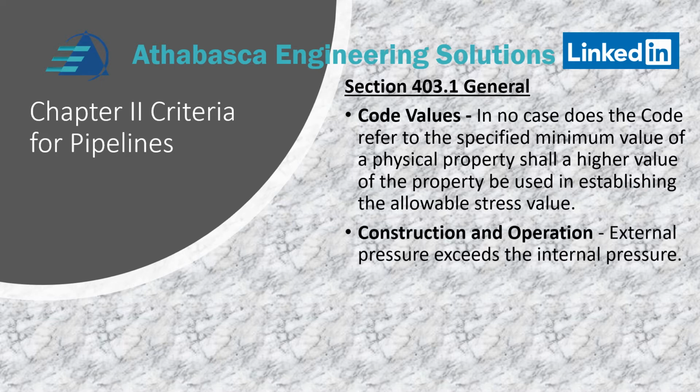Secondly, during construction and operation, external pressure can exceed the internal pressure because when a line is pressurized, for example, it can handle a lot of external loads because the internal pressure offsets the external pressure. So during construction and operation, this must be considered.